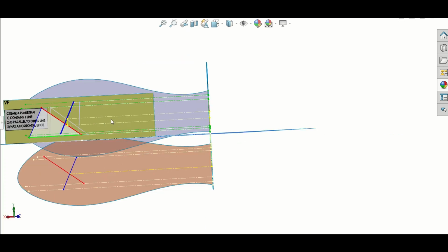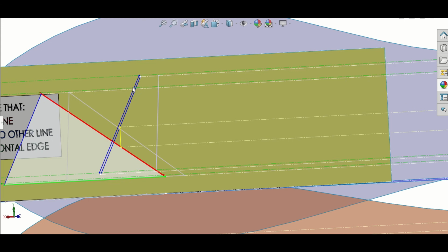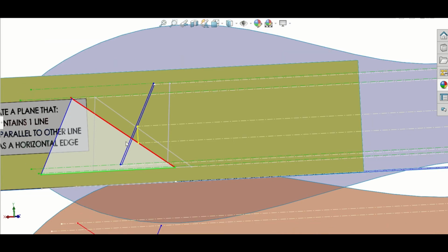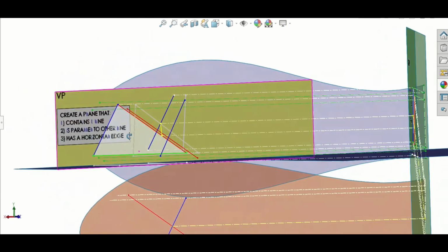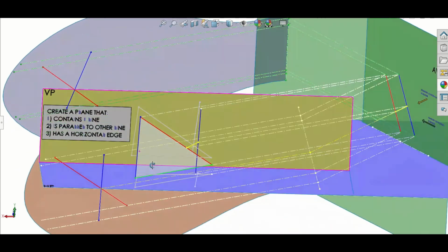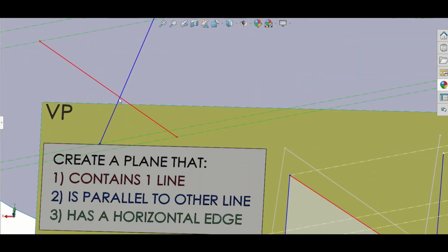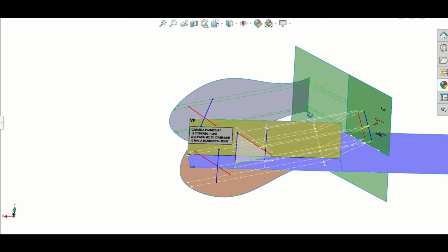My projections, we can see they're just slightly off there, but they are perfect. It's just that turning in SolidWorks doesn't always turn perfectly. The two lines as they appear are at the back of my three-dimensional model right there. And that point where they appear to cross represents the point view of the shortest horizontal distance line.